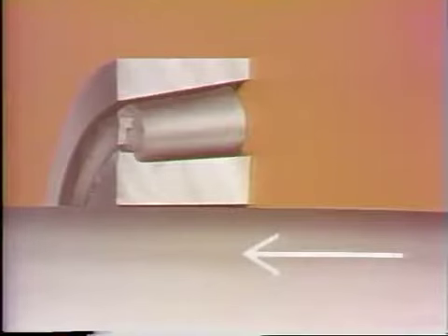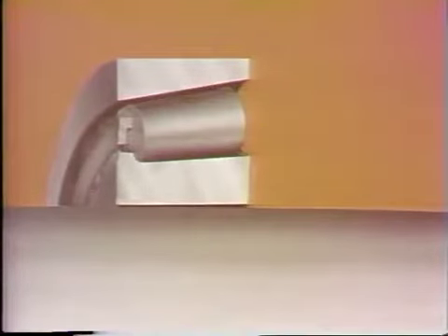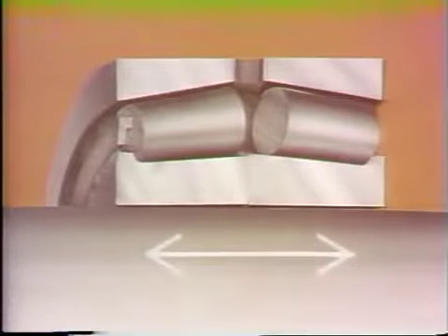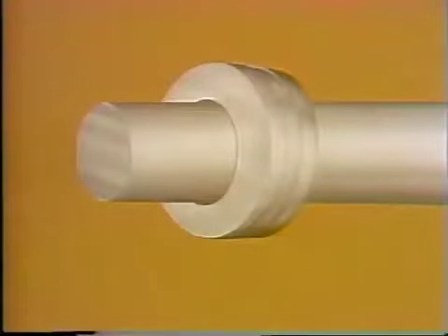If the shaft tries to move this way, the rollers meet the outer ring and the shaft is unable to move. Now remember, lubricant in the bearing prevents actual contact of the parts. This bearing will prevent axial movement in this direction only. But the addition of a second bearing will prevent axial movement in both directions. A rolling contact thrust bearing, which prevents axial movement only, is designed differently.